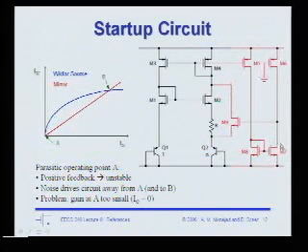So this kind of looks like a logic gate. If this current is zero, then this point gets pulled up to supply, right? And if that happens, M9 turns on, right? So now M9 turns on. That's because this point is also about ground, right? Because there's no current in the circuit. So M9 turns on hard and pulls current out of M4. Great. That gets us out of the